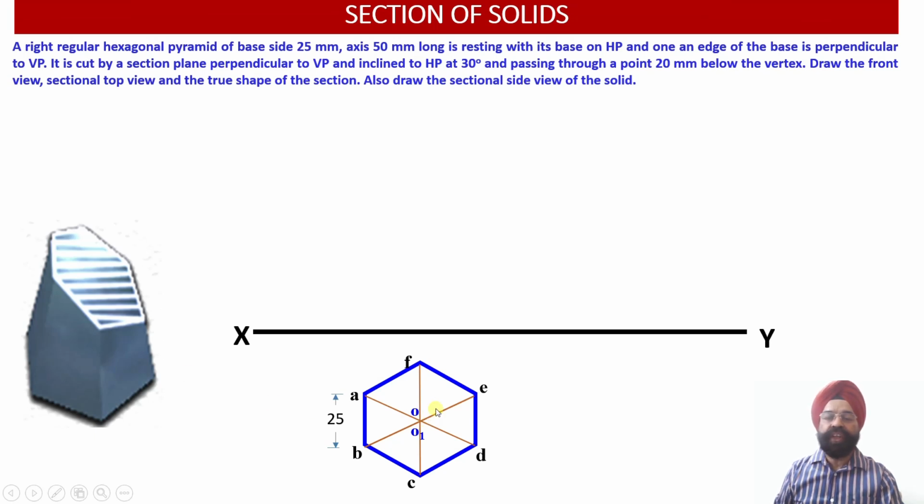So now draw the front view, because the base is resting on the ground. So the front view corresponding to the base points will be located on the XY reference line.